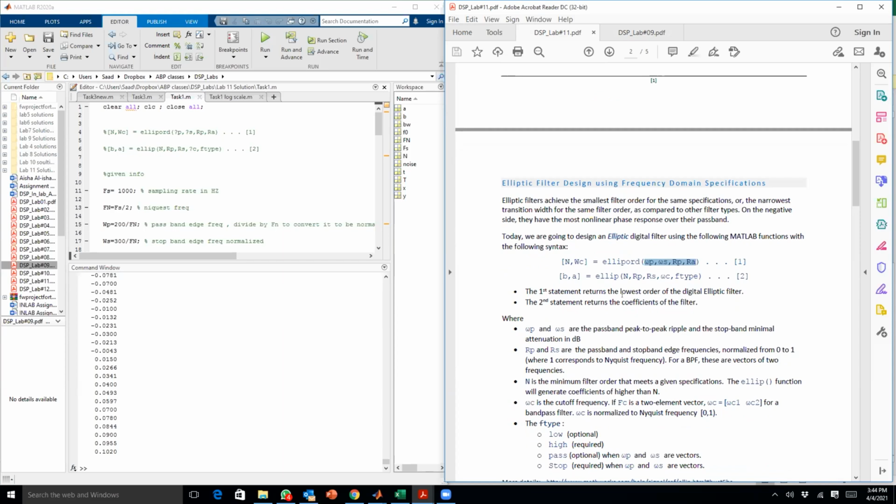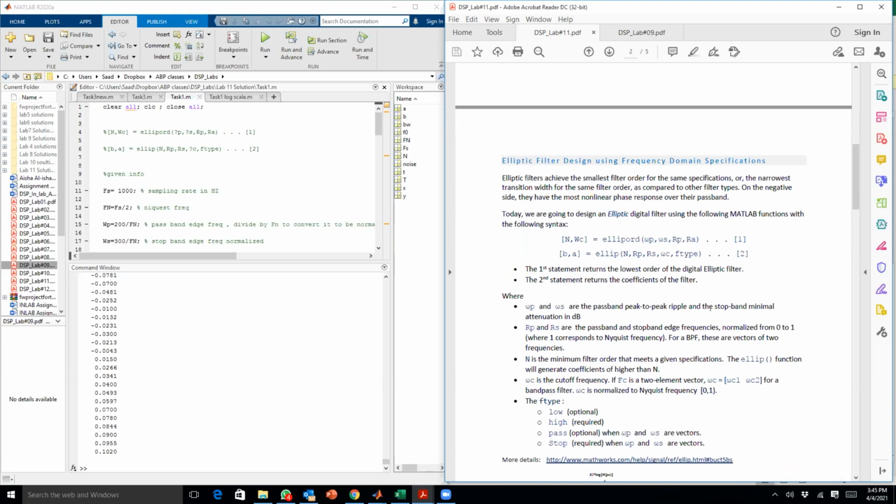When we get the poles and zeros, B and A, B are the zeros and A are the poles. We also need the order number, which we get from the first MATLAB command. Then we give Rp, Rs, Wc, and the filter type. For the filter type, we need to tell it whether it is a...